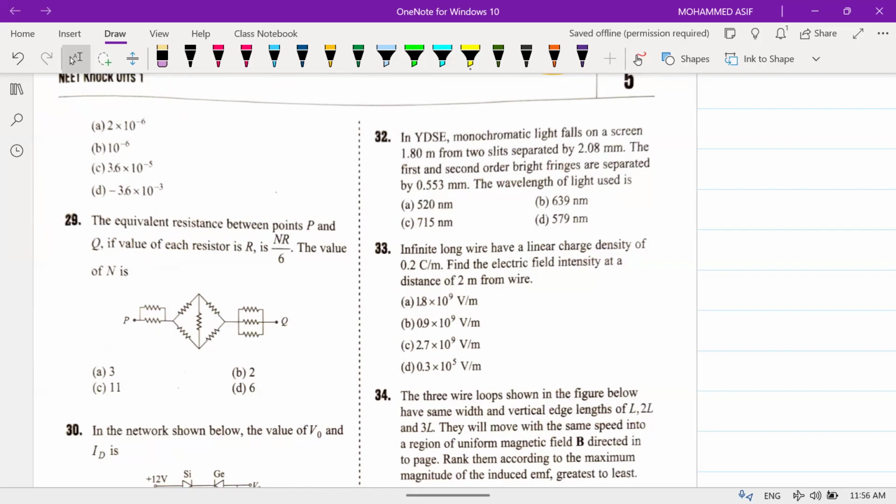You just need to identify which are series and which are parallel. Now see, I'll get the equivalent resistance. Say for example, each of them has a value of R. This one is R. This one is R. These two are in what? Parallel. This is a Wheatstone bridge. In the Wheatstone bridge, P by Q is equal to R by S. This will be ineffective. That means between P, we have one resistance. This will be equal to R by 2.